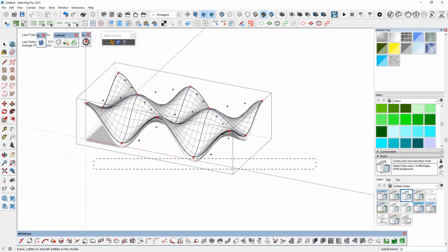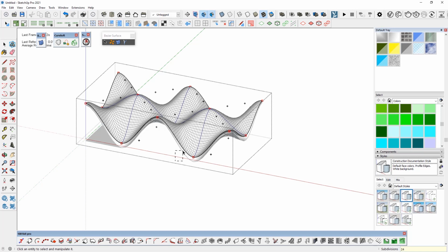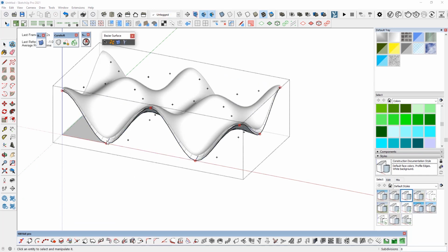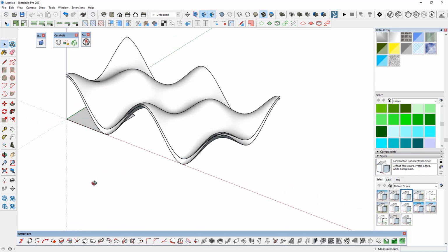The next process is of course to connect both those surfaces with curve loft, but before we start it we need to increase the subdivision to get a smoother surface. We couldn't do this at the beginning because it would be problematic with selecting the correct vertex. So now we select the surface and on the keyboard we put 24 as a subdivision.